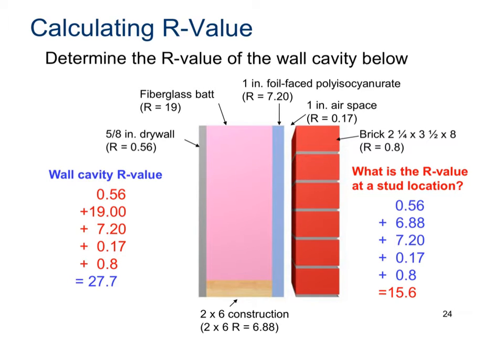In this video, I'm going to talk about calculating that R value if you've looked up your R values on a table or if they're given to you in the problem. All right, with R values, you can just add up the R values that are given for each of the layers in your wall or whatever it is that you're looking at.